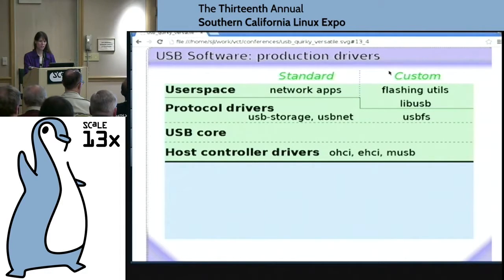Whereas you tend to care a lot more when you're dealing with those custom protocols, because on top of the low-level generic access, you tend to use the library called libUSB that is a nice wrapper for your custom stuff. And I've seen things like reflashing utilities that end up getting built over libUSB. There's no standard USB class that says how one must flash a new firmware onto your FTDI part or whatever.